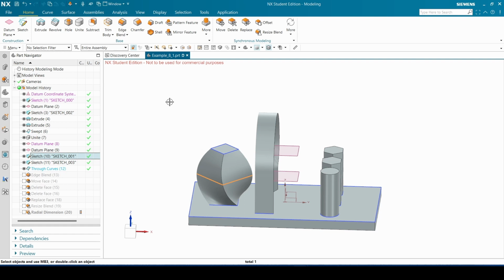The other reason is if you get, in air quotes, a dumb part. If there's nothing here, it just says it's a body. There's a coordinate system and there's a body. You don't have a feature tree for it. This will be common if you get, for instance, a Parasolid file, specifically from someone who used another CAD package.